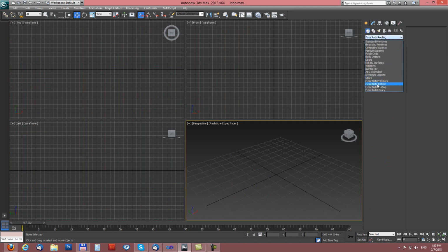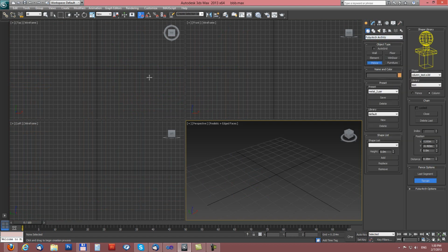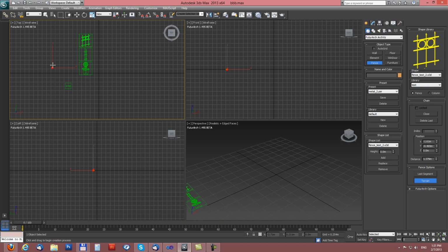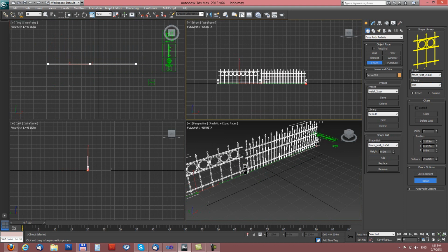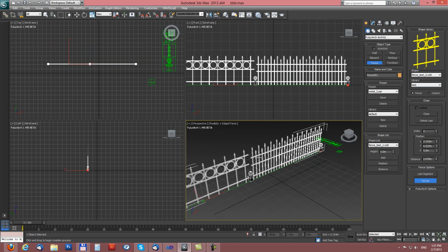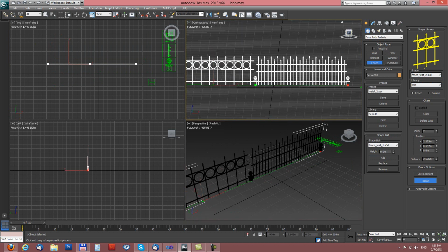So I'm going to Archviz section, activate fence tool, clear shape list, and in column library test folder column test object I will add our added column. In fence library also test folder we can add fence test1 and fence test2. Clicking into viewport, I will draw the first fence element and second fence element, and we can see them now very nicely in the viewport.